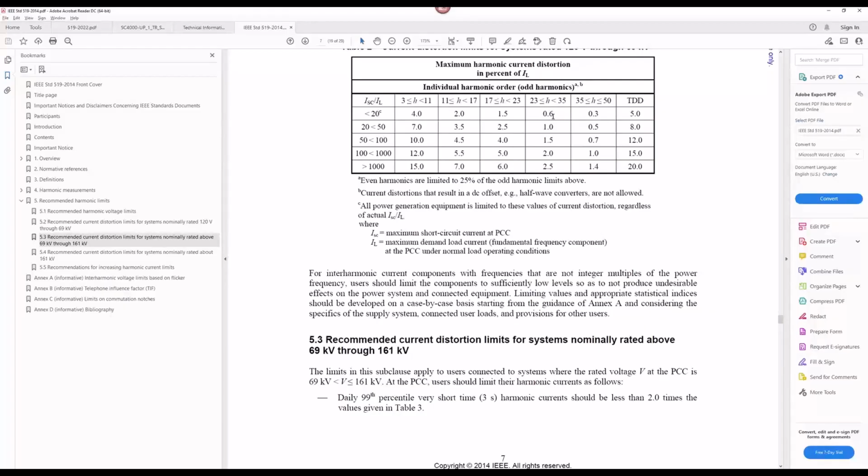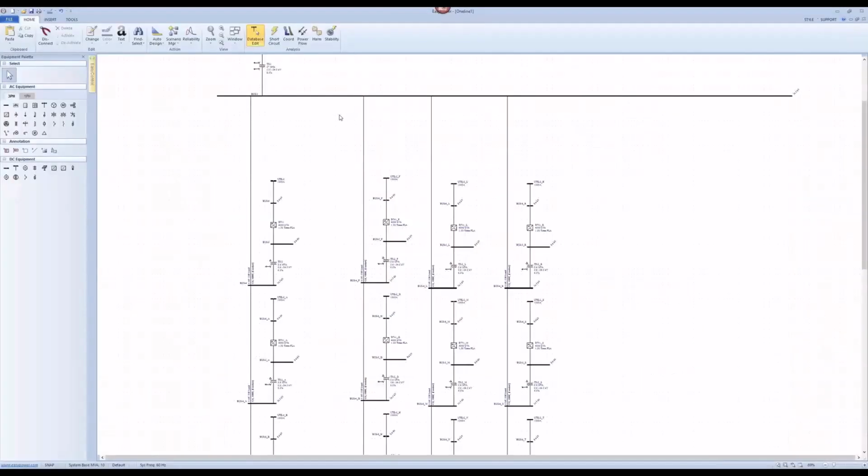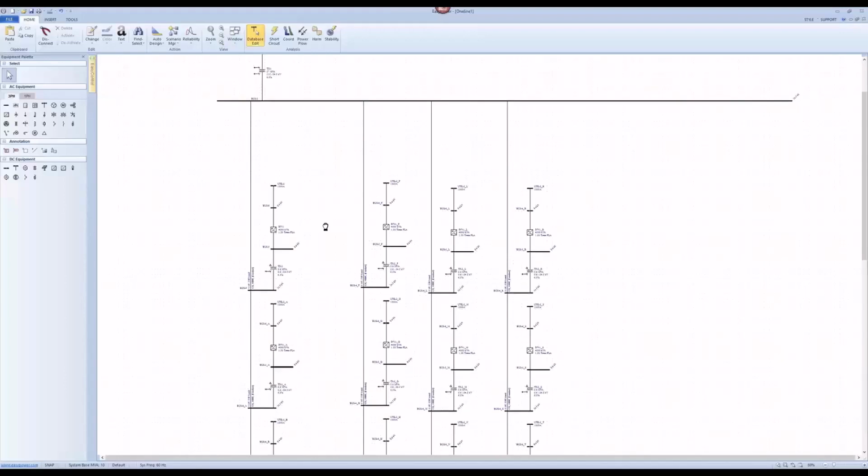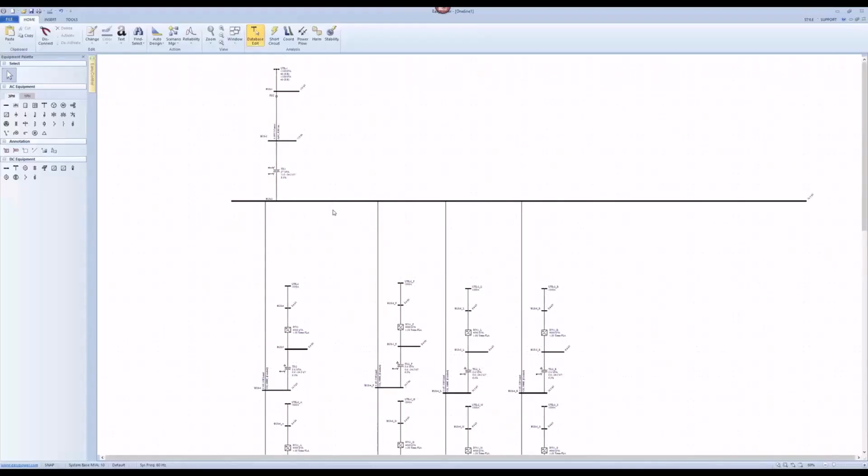So usually what we typically do is install a harmonic active filter to absorb those harmonic injections for the high order, or install a passive filter at 34.5 kV to filter them out. Usually a passive filter works as a low impedance path to the ground to redirect the harmonic current from flowing through the transformer, and instead flow to the ground. So that's a typical way. Now let's go back to the original question we asked at the beginning: why do we feel like a capacitor bank, which is typically used in the power plant for reactive power compensation, is not a good idea.